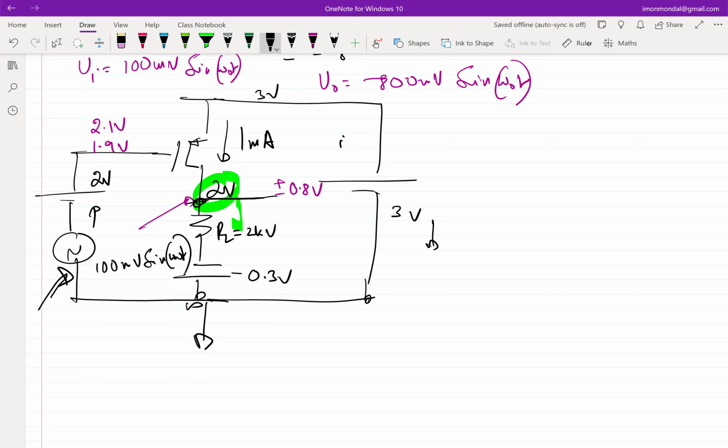So let's not get into that right away. So let's assume that cannot be done. Negative voltage cannot be done. What else? Increase the resistance. Okay, so let's increase the resistance. So if I increase the resistance, can you comment on the drain voltage for the same quiescent current?